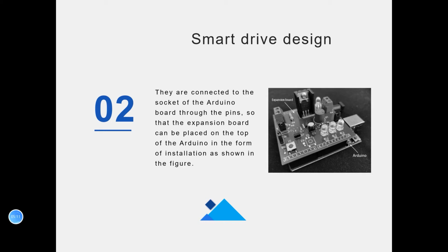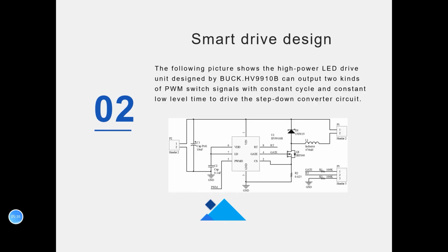Digital pins 8 to 10 are used to drive 3 low power LEDs in the indicating unit, bright and dark respectively representing binary numbers 1 and 0. Their light or dark combination can indicate PWM signals with different duty ratios.